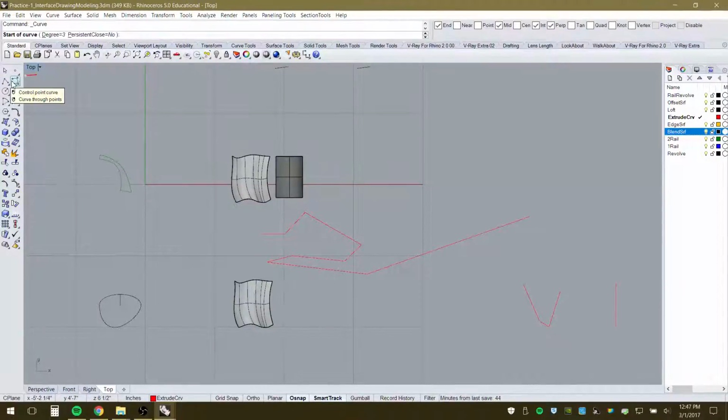This is for the free-form curve, so you can start to see here that I'm creating a series of points, but gesturally it's averaging those overall to create these different curves. You notice that there are points that were created when I created both of these curves. Those are called control points. There are control points for lines and they're control points for surfaces.